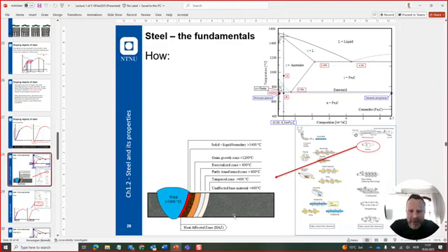What takes place where the ground material has not completely melted is an increase in grain growth. Grains are growing. They are melting together to bigger grains. Bigger grains, larger and more grain boundaries. Grain boundaries typically being weaker than the solid grains themselves.